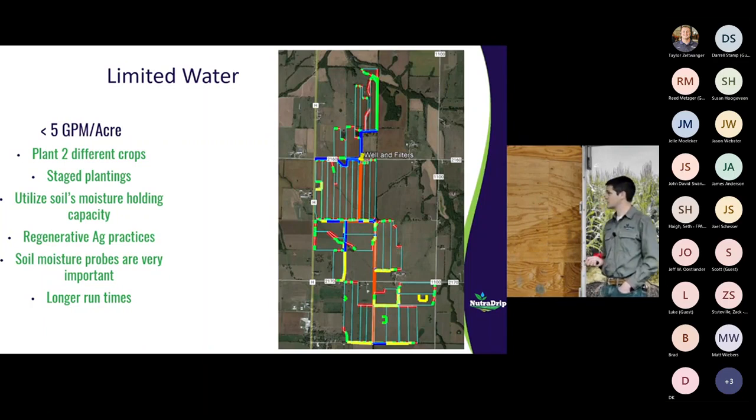This past year, this has really stuck out to me, longer run times. On his particular field, we were running 8-hour sets every day. So every day we were watering the corn, just a little bit of water. And that corn was so thirsty, it was pulling the moisture basically as fast as we could put the water on, it was pulling it away. So our wetted bubble of water was very small. The roots were exploring very little of the soil. So there was a lot of nutrients we weren't having access to because it was so bone dry except for that small circle. So running for a full day and then skipping a few days and running another full day or whatever, again, it's going to come back to your soil type and how much water you have. I think we'll see a lot of benefit from that.